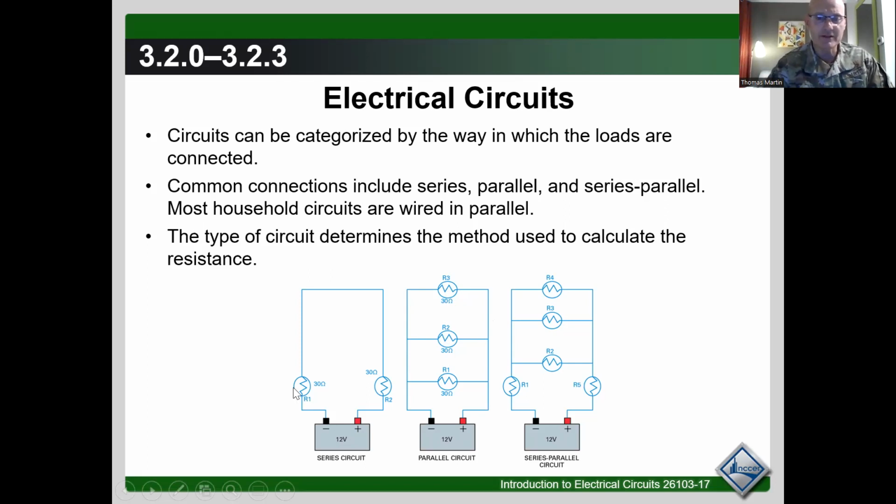Now look over here. If this lamp blows, then this light won't work because I can't point at it with my hand and illustrate. But imagine this. We're going to say this is the resistor. If this blows, the bridge is open. Electrons can't flow from here to here if this is blown, right? So therefore, the circuit's dead. Now, over here in the parallel circuit, it gives me an option. Let's say that R2 right there blows up. Pops, guys, goes away. I can still operate on R1 and R3.